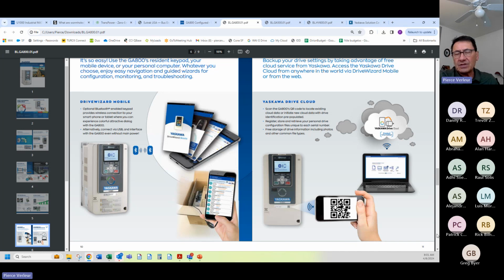And it's a 5-channel or 6-channel scope. You can basically chart 6 different parameters from the drive's data read-only registers, like current, output voltage, heatsink temperature, et cetera, et cetera. So a very, very capable product.